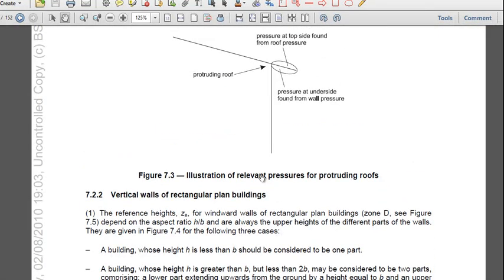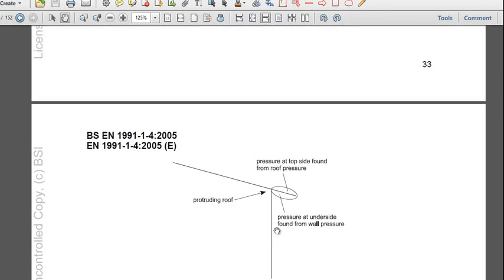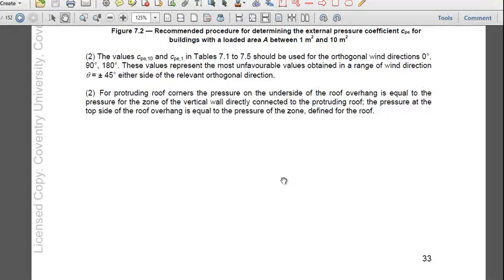Now, when you're calculating the dynamic wind pressure, you typically would have to calculate the dynamic wind pressure in orthogonal directions for doubly symmetrical building structures on plan, as the code requires. Okay, so it specifies a plus or minus 45-degree directional range, with critical wind attack directions in orthogonal directions being more onerous.